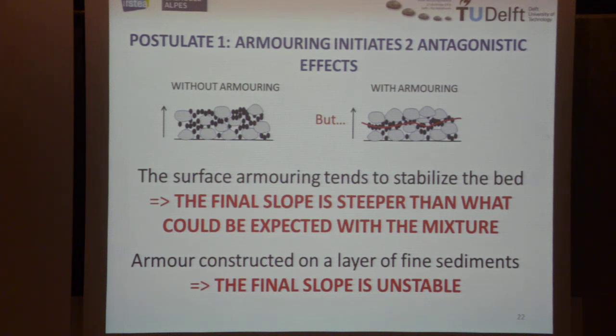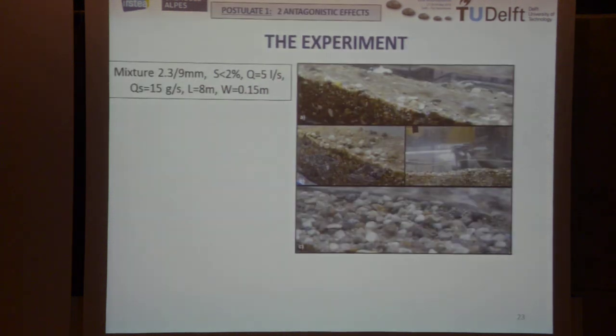This is the antagonistic effect. We create a bed which can be, in appearance, stronger and more stable, but actually this bed is fragile because below you have built this kind of fine sediment over which reposes the coarse fraction. I will try to illustrate that.